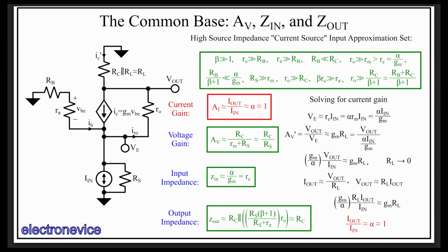Now, the ideal output impedance of a voltage source buffer is a low impedance output. This allows the buffered voltage output to be unaffected by changing current draws and maintain a copy of its input voltage on the output. Conversely, the ideal output impedance of a current source buffer would be something that would maintain a good copy of its input current regardless of what impedance is on the output. So a high output impedance is the ideal impedance of a current source buffer, as that would maintain an output current close to the input current regardless of the impedance on the output it is connected to.